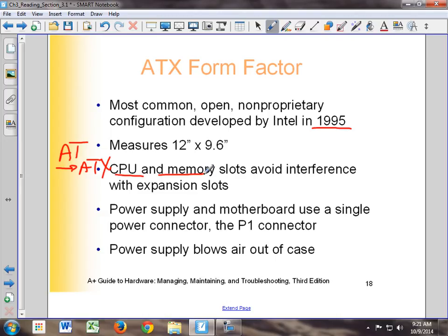Okay? It's bigger, but it still goes back panel, CPU, bigger CPU, and memory, just like this does: back panel, CPU, memory. All the expansion slots are down here, so they're out of the way of that stuff. And that's how I can have the same holes work the same, because I just extend down and then I get more holes. These basic holes right here, this one, this one, this one, and this one, are the same on all ATX. And then if the case gets bigger, I get holes here. If it gets bigger up here, I add more screw-in holes here. I'll show you a picture of that here in a second.